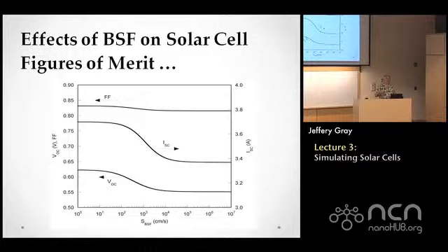Then you could tie that to, in this particular case, a doping level for the back surface field to see how close you can get to the ideal case. But clearly there's a lot of improvement you can gain by having a back surface field. The short circuit current can drop by about 3 parts out of 36, so it's almost a 10% effect on the short circuit current. And you can also see it's a significant effect on the open circuit voltage over here.